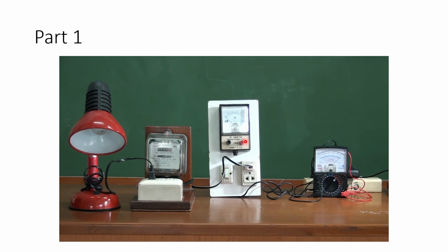The other thing that you can do is measure the current directly and measure the voltage directly. And this one is a little bit dangerous, so be sure to set this to AC voltage of 250. As you know, the voltage in our household is 220 volts, so the voltage is pretty high. So be careful with this. You get 220 here, and then you read the AC current here. Multiply these two, and you should get P equals IV for the wattage.